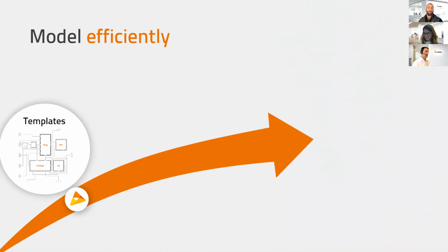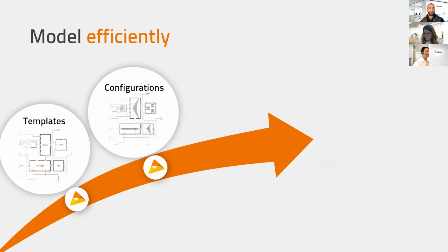Within Modelon Impact, we then use object orientation to make large-scale modeling efficient. As you can see here, we start with predefined templates. And if we take layers of these, we define our model architecture. And within these templates, we have placeholders. And when we're populating these placeholders with specific modeling assumptions and parameterization, we create architecture configurations.